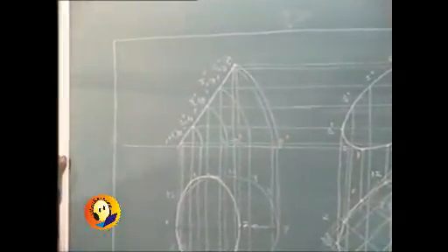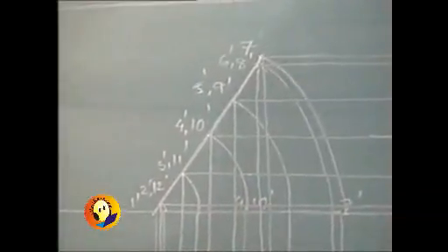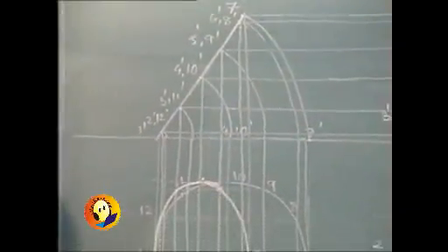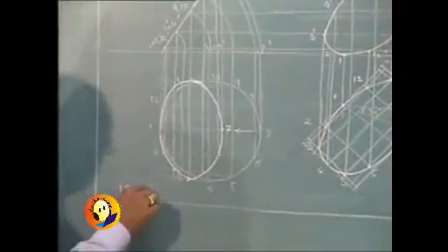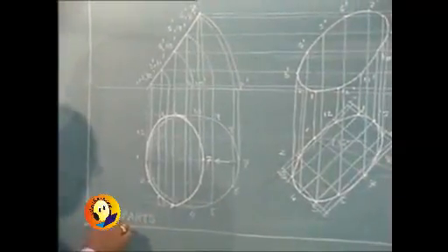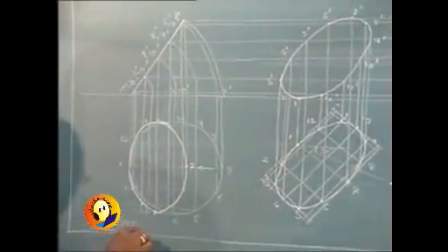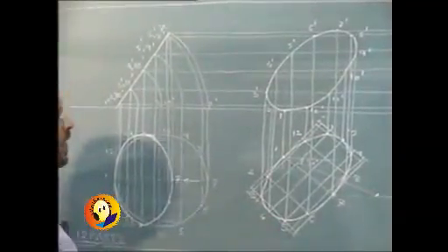The projection of a circle is minimally to be divided into 12 parts. It is essential that we will have to divide every circle into 12 parts, otherwise we will not get the required smoothness. The figure has been transferred using the rectangle technique.